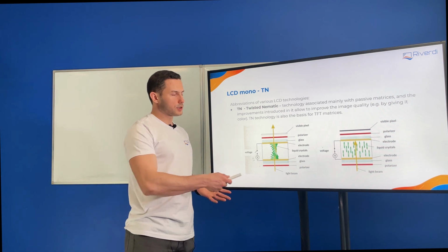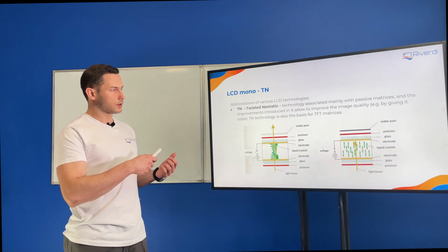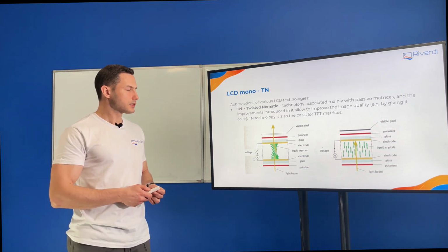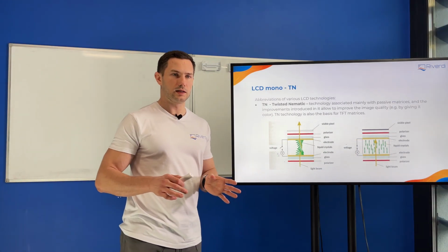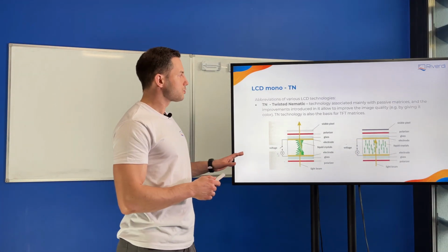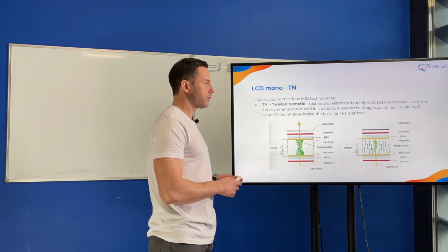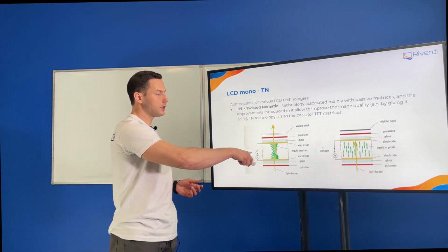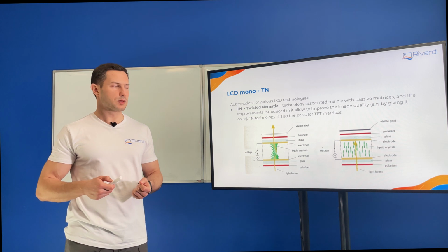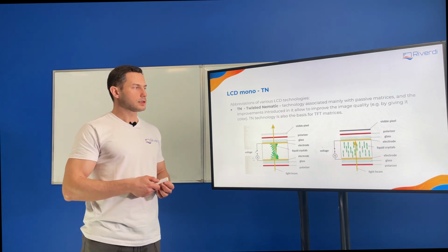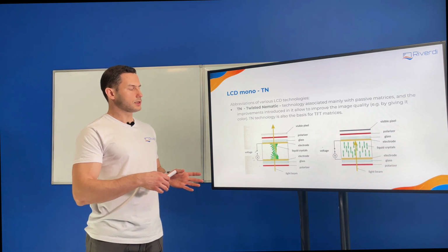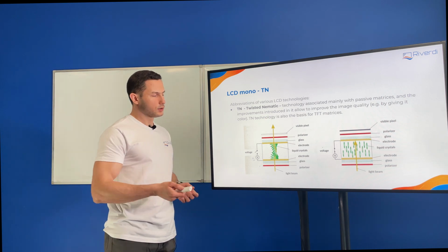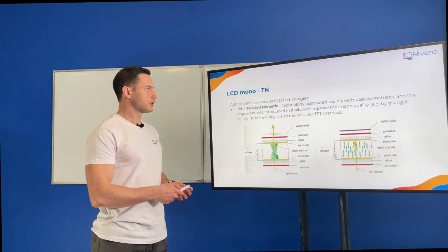So this technology actually allows us to have a display working and present some images with the grayscale, but in a normal LCD, the monochrome LCD displays, it's usually not used because the technology is not perfect enough. It's a passive technology. There are no transistors connected to the cell itself, and controlling the brightness with the grayscale is really hard. So usually it's not done here. It's used in the other technologies like TFT that we'll be talking later, but here we usually have only on and off state to have the clear image.